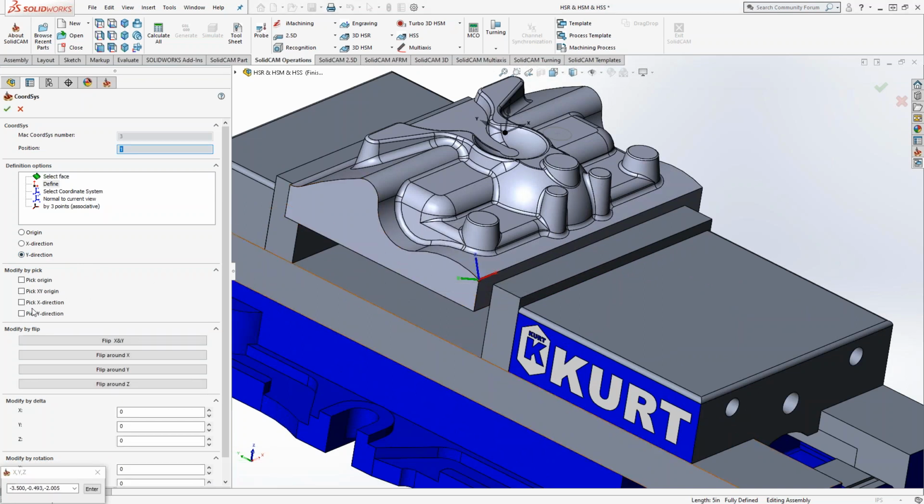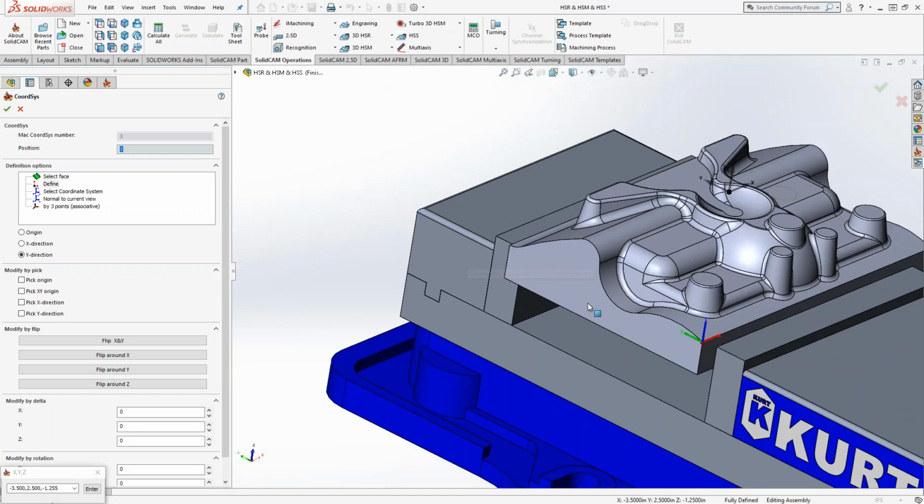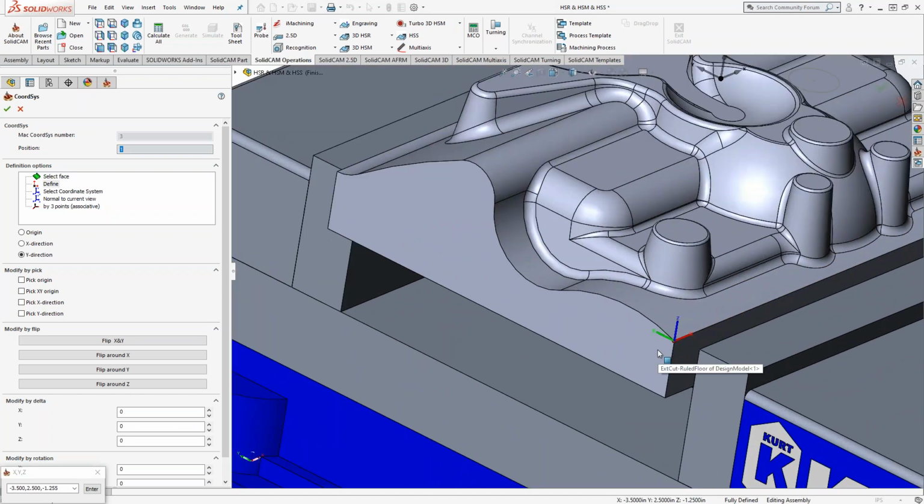Or that actually is grabbing the point. So let me just reselect that. Let me try and get that vertex there. There it is. So x and y gives me z. So same as before. You choose the geometry that's on screen. So if you had some straight line edges of your part, of your solid, or of your surfaces, or if you just have a point cloud, you can select those.